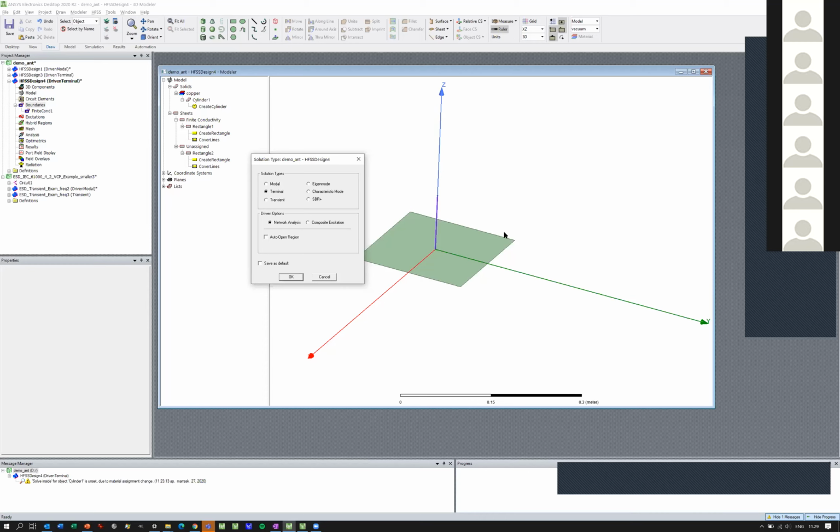Easy way to do the boundary condition is to click here, outer region. And now I'm specifying a radiation boundary to my setup. And that's typically good to start with. These are more accurate. Oh, sorry, this is more accurate, but it's more heavy to simulate. So I'm using a simple radiation. And this is a hybrid where you can specify surface currents. So this is one way, easy way to define the boundary condition. So just go to HFSS, solution setup, and outer, and that's it.